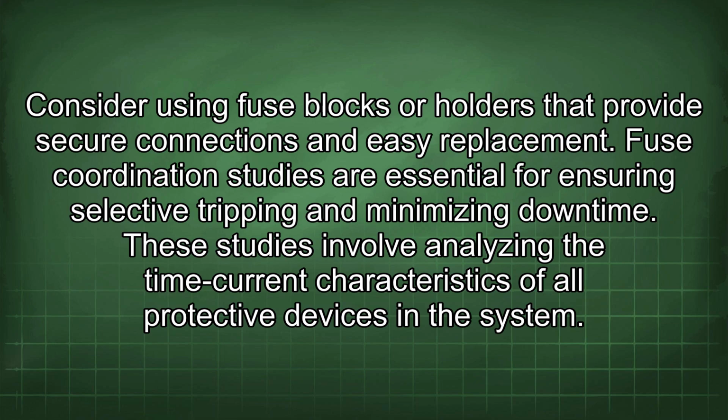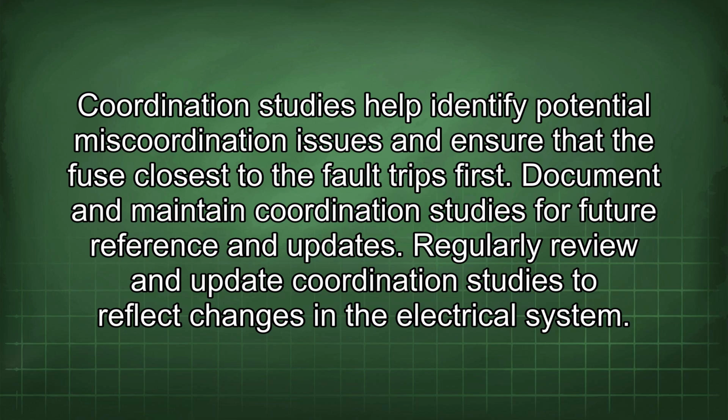Fuse coordination studies are essential for ensuring selective tripping and minimizing downtime. These studies involve analyzing the time current characteristics of all protective devices in the system. Coordination studies help identify potential miscoordination issues and ensure that the fuse closest to the fault trips first. Document and maintain coordination studies for future reference and updates. Regularly review and update coordination studies to reflect changes in the electrical system.